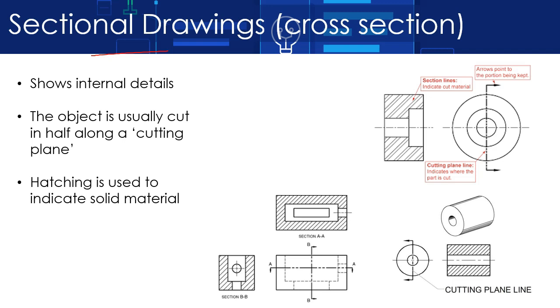So building on that, a sectional drawing is basically a cross section. So sometimes on a drawing you can see lines like this that go through a component, and then it will say, look, this is what it looks like if that was a cutting plane. This is what the inside of the product would look like. And it can show you things like, you can see there's a little bit of a kind of a recess there before the hole carries on all the way through the product.